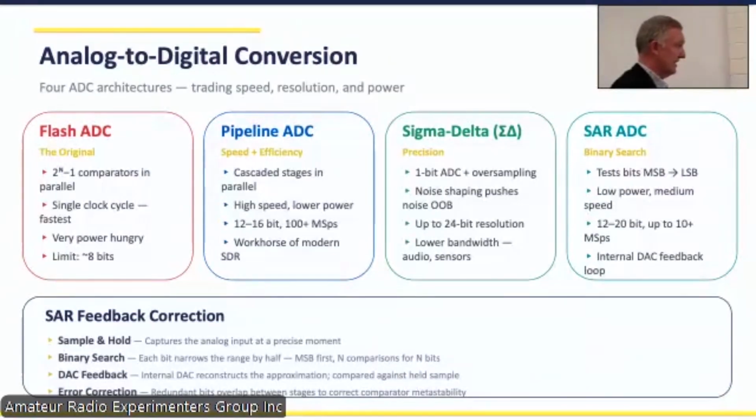Then the improvement of the inline flash process is the SAR. And the SAR, and I've just lost the terminology, is a feedback mechanism which you'll see in some of the radios that they look at their output signal and compare it to the input signal and then adjust the input signal such that it's corrected for any non-linearity. This is what's done purely inside of the ADC. So it comes in analog, it's converted to digital, it's converted back from digital to analog as a part of the feedback, and then it's compared to the original signal. And that's done on each bit.